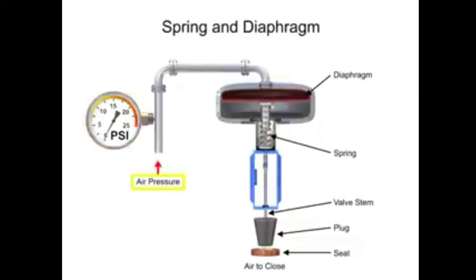As pressure is exerted on the diaphragm, a downward force is applied against the spring, which moves the restrictor. The diaphragm moves until it creates an equal but opposing force against the spring, at which time the motion stops as the plug meets the valve seat. With no air pressure, the restrictor is pushed upward by the spring to act as a normally open control valve.